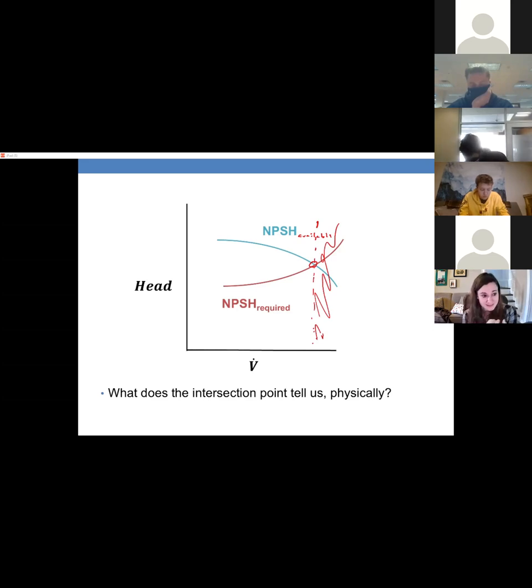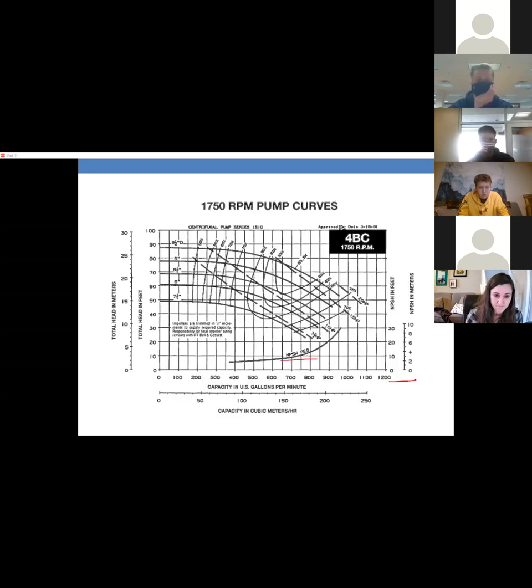It's swirling around in there. It's got a suction sucking it in. There might also be stagnation points and points where there's losses and vena contracta and all that junk. So pressure is going to drop lower at some point inside that pump. So it's kind of like a pump curve? Exactly like a pump curve. We know we need some extra head basically to account for stuff that happens inside the pump, and the way we find it is just through experiment. Okay, that makes sense. Thank you.